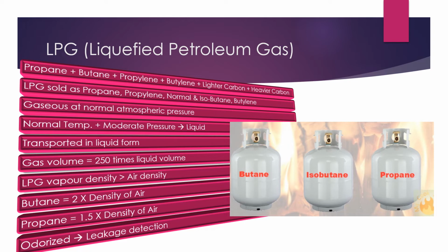As the volume of LPG is 250 times the volume of air, even small amount of discharge or leakage of these gases will be converted into large volume of vapor and air mixture. This has a lot of potential to cause substantial hazard. Odor is added to LPG to identify its leakage. The storage of LPG at ground level should be adequately ventilated. LPG should not be stored in cellars, basements which have no ventilation at ground level.